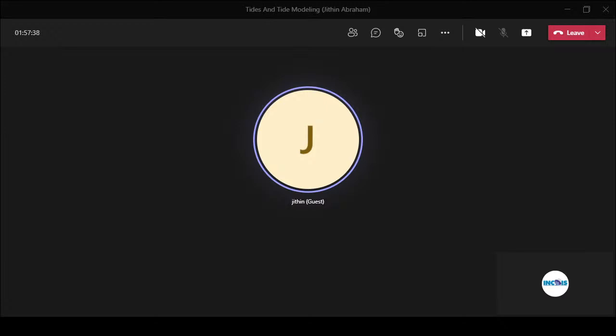The easiest way to measure the internal tide is from moorings or buoys. They have a temperature sensor as well as ADCP. In that way you can measure the internal tide signals, but you need very high frequency measurements, at least with an interval of a day. If you have that data, you can extract the internal tides from the measurements.